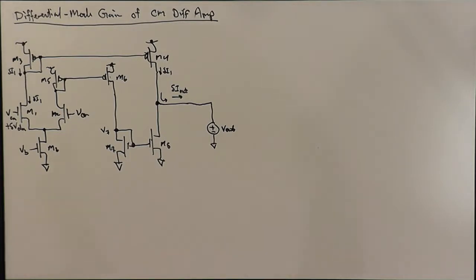Yet a third way of looking at it is the idea that it sees a current divider and it goes for the highest conductance path or branch, and the ideal voltage source has basically an infinite internal incremental conductance, and so all of the current will flow into the voltage source from that point of view. So that's half of what the delta I1 does.